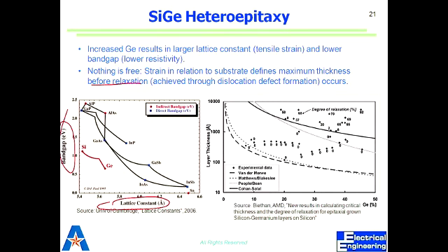It's not a diode, but yeah, built-in potential threshold voltage is more related to a diode, where you have a PN junction and you have to bias it to make it work. But isn't there a difference? Like in a diode, you want to go above the threshold. In the MOS capacitor, you wouldn't want to go above the threshold. Right, because you're breaking down the oxide. Right. But the threshold is there for the same reason, right?